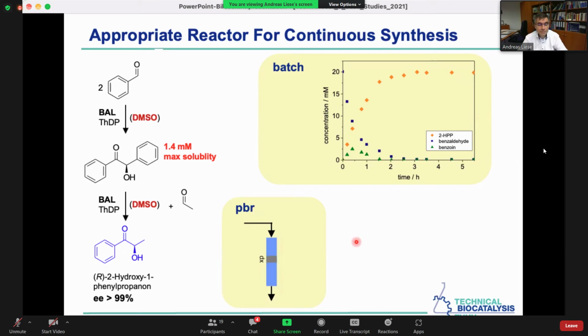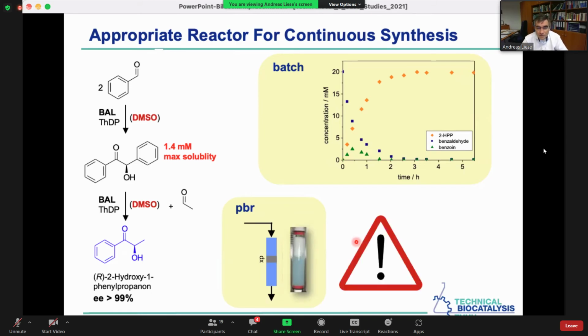The technician goes for a coffee break after starting up, because it was clear it was running without any question, and then comes jumping back to the lab after the coffee break because suddenly this column looks like this. This bluish color, which was the whole column before he went to the coffee break, is the immobilized enzyme. And when he returned, the pressure was up, and here at the inlet, the color has changed significantly to white in the first third of the reactor, the first quarter.